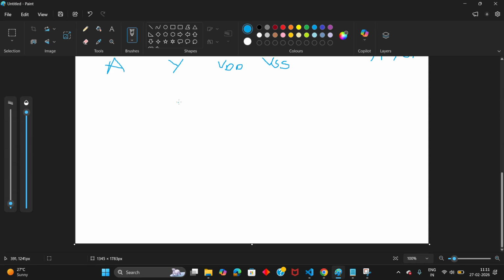Next, what I have told is, in the pull-up network we are going to have the PMOS, and in the pull-down network we are going to have the NMOS. The point you need to remember is, here we are going to have only one input, that is A. So in the pull-up network you are going to have only one PMOS. Similarly, in the pull-down network you are going to have only one NMOS. Always the PMOS count and NMOS count will be equal to each other in CMOS technology.